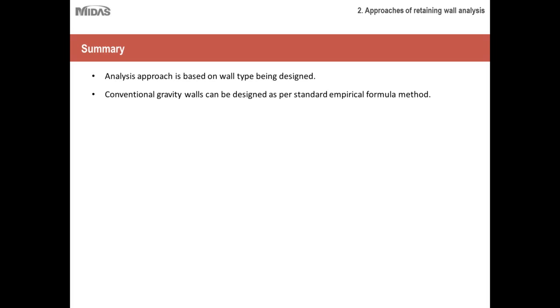For conventional gravity walls, you can design as per the empirical formula method that we have been learning and using in school. For MSE wall, we need numerical analysis for the estimation of deformation and stresses during construction.